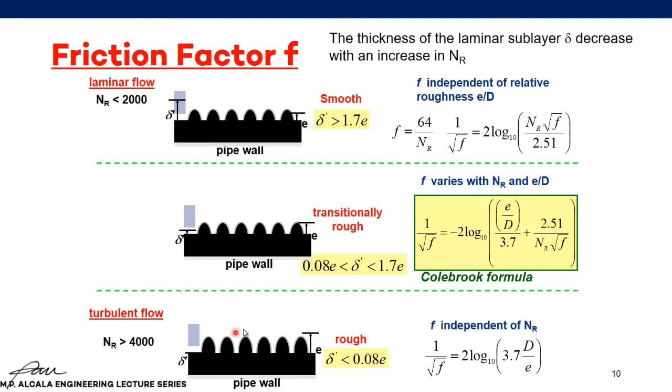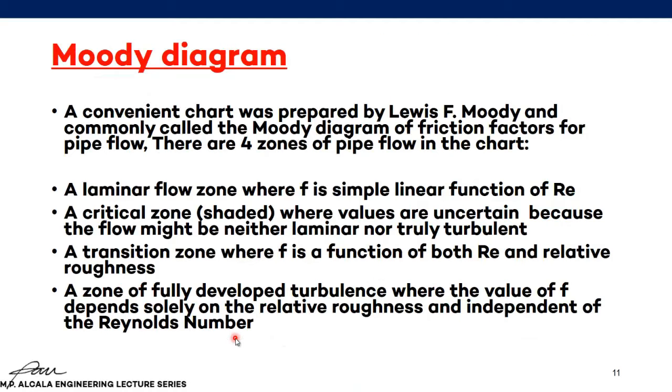Essentially, there will be chaos in your flow, right? There will be disorder. That's why your turbulent flow can be seen in your rivers, in your flash floods, in your raging waters, okay? Your turbulent flow is where the Reynolds number is more than 4,000. So smooth sailing, rough flow, okay?